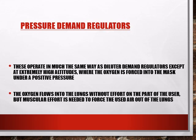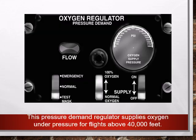Pressure demand regulators ensure oxygen delivery at very high altitudes, above 40,000 feet. The system forces pressurized oxygen into the lungs during inhalation. The high pressure, combined with 100% oxygen, keeps the oxygen's partial pressure high enough for the lungs to absorb a safe level of O2. Since the system forces air into the lungs under pressure, one will need to force it back out during exhalation. This can be exhausting. This is a diagram of a pressure demand oxygen regulator showing the oxygen supply pressure.